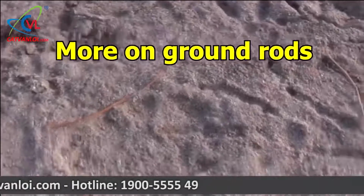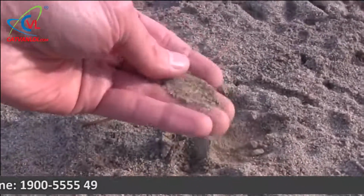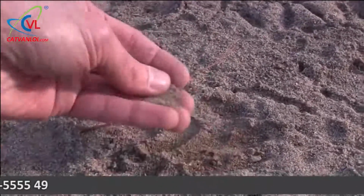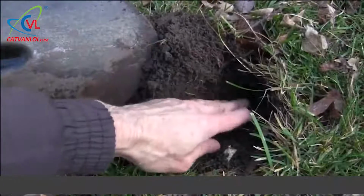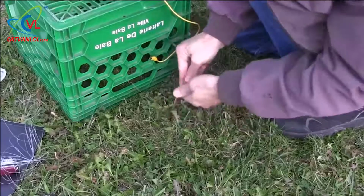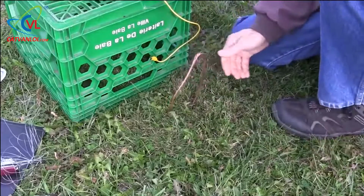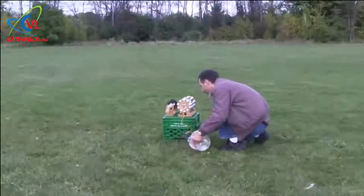For a ground rod to work well, the ground does have to be electrically conductive, meaning it has a low resistance. Dry sand like this is not very conductive, and is a bad ground. But moist soil is fairly conductive, and is a better ground. Also, the more ground you connect to, the better. Here I just pushed some wires into the ground, and it wasn't very good. I even poured water in to help, but it still wasn't great.